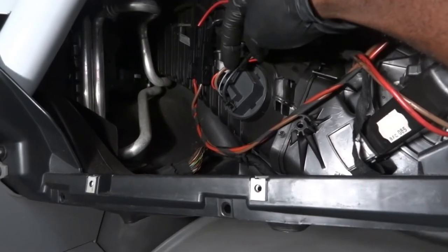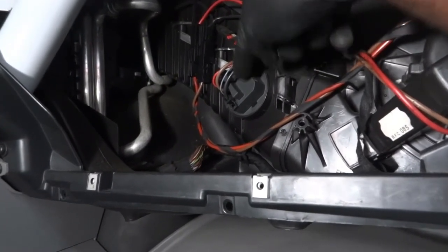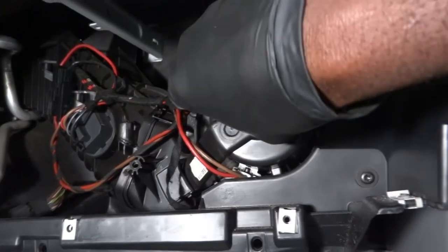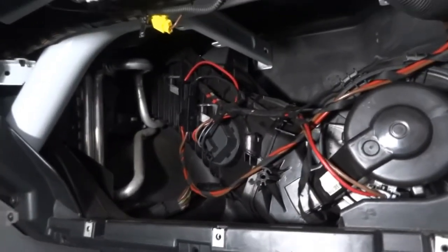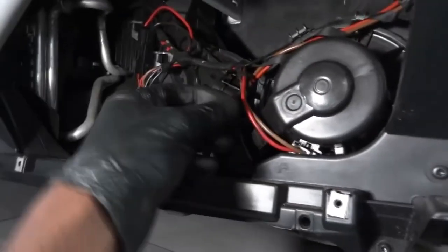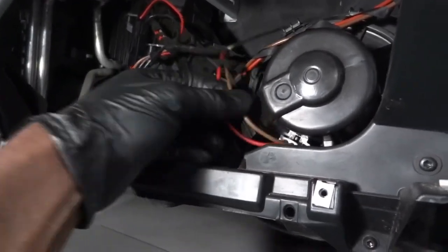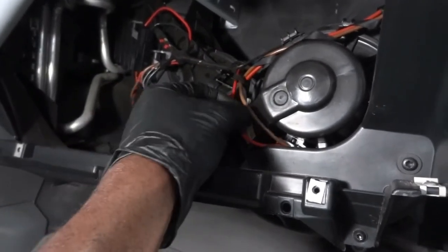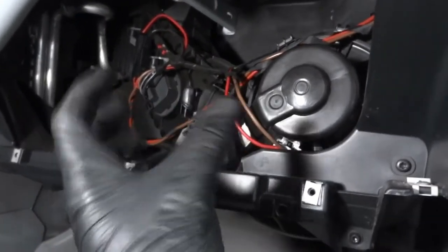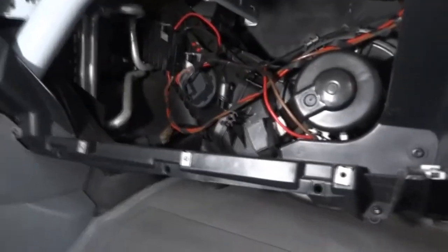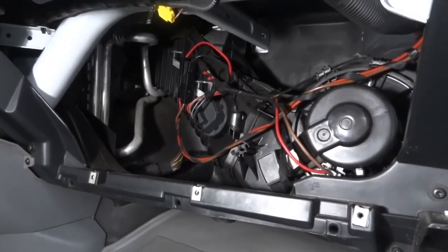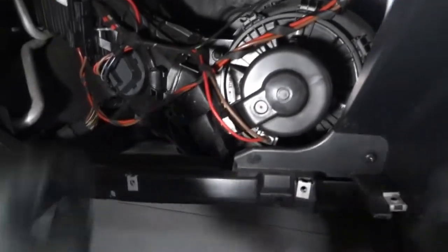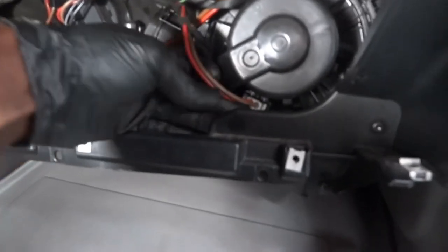This wire, it commands, it tells this regulator to send the correct amount of ground to this blower motor, so that the blower motor can turn at whatever speed that the driver commands it to. Okay, there should be a constant power supply on this wire, and then there is varied ground on this. So this regulator just varies the current flow on this wire, okay, to increase or decrease the blower motor speed. So we don't have to get too fancy. Let's just remain low tech here. This is not really hard to diagnose. I hope it's just gonna end up being a blower motor, which I suspect is gonna be the case here.